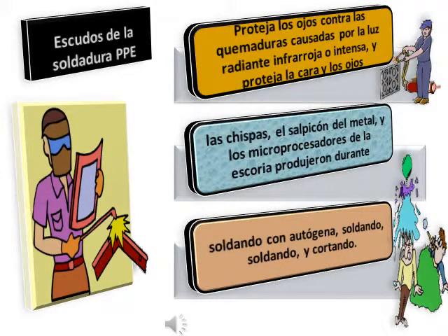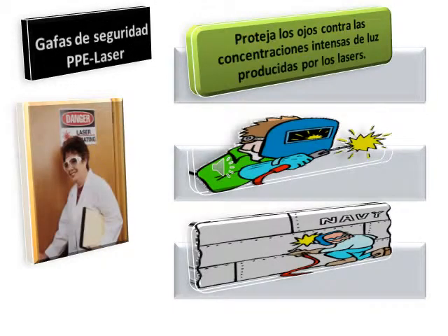Protect your eyes from burns caused by infrared or intense radiant light. And protect face and eyes from sparks, metal splatter, and slag chips produced during welding, brazing, soldering, and cutting. Laser safety goggles protect your eyes from intense concentration of light produced by lasers.